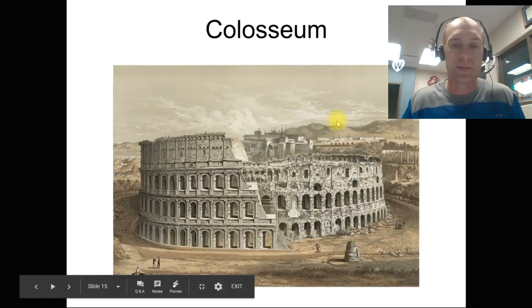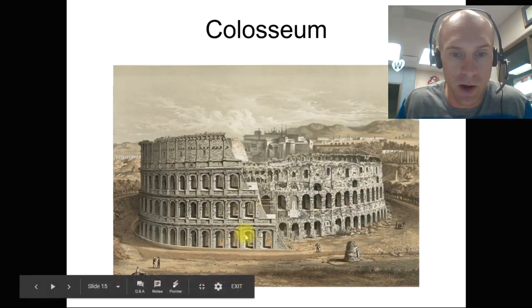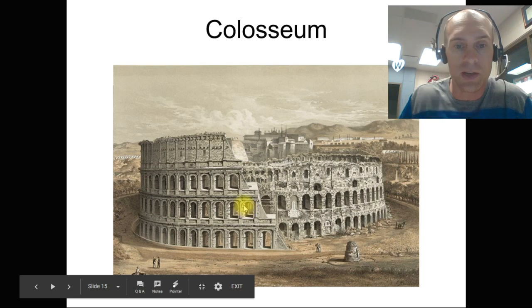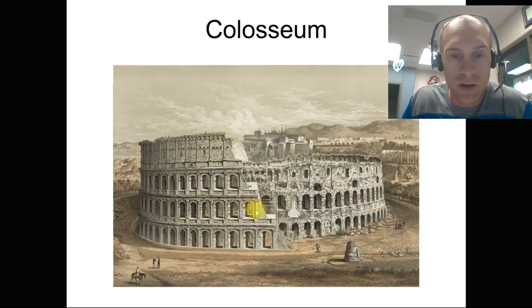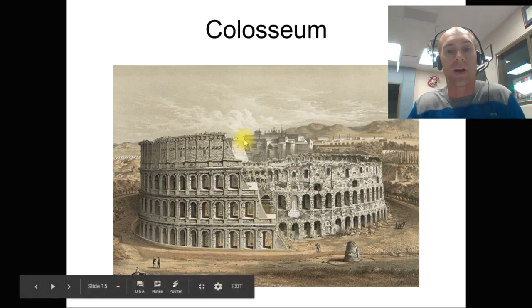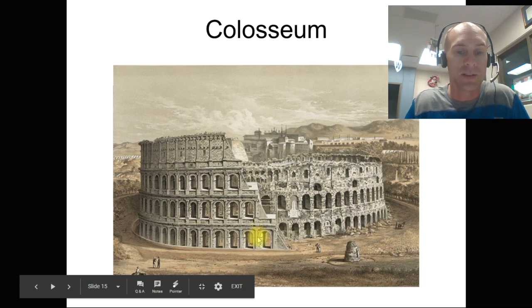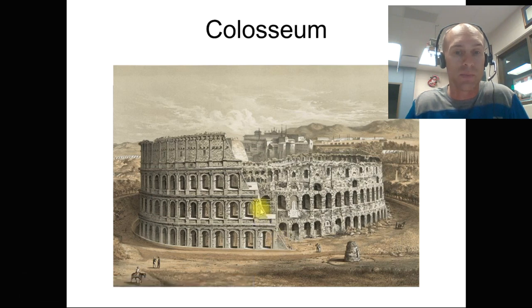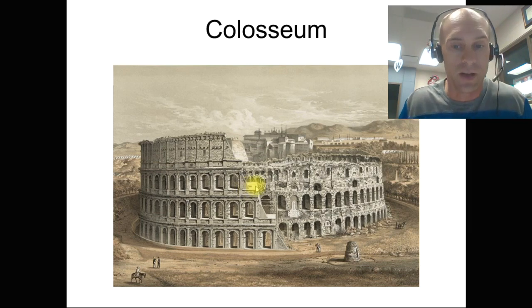The Colosseum is an amazing example of these arches, and note, just like what we were talking about before, anytime you have an arch that's on the very end, you have to have all this mass on the side to keep it from spreading out to the side. So that's why the Colosseum has these stone piles on the outside edges. On this edge, it's pushing left, but this arch is pushing right to support it and balance that out. But again, the very outside one needs weight here to hold it up. So that's why the outside edge of all these arch rows has all that extra mass to it. Oh, they're so smart.